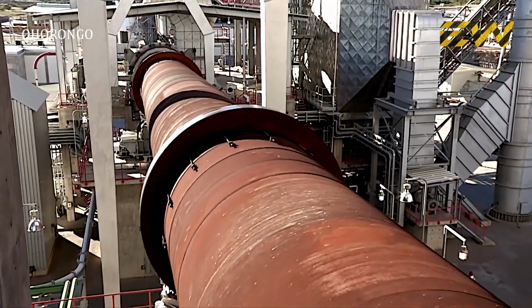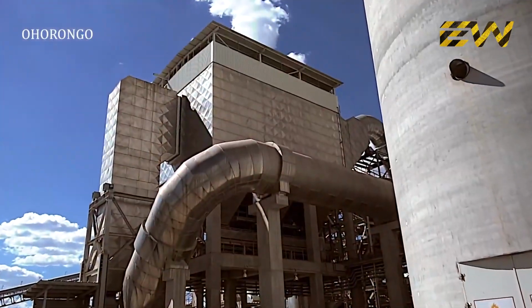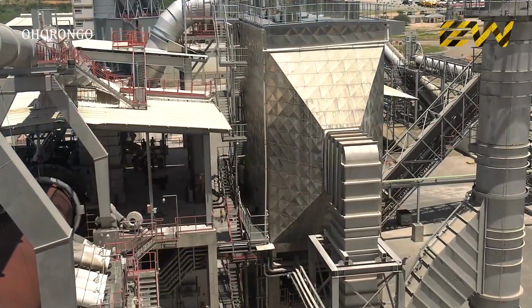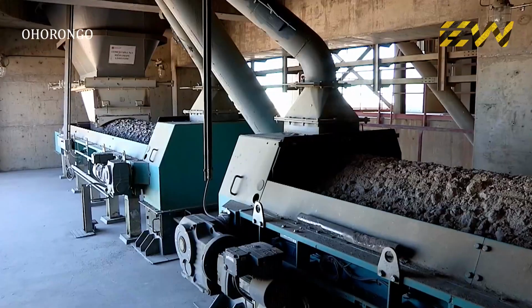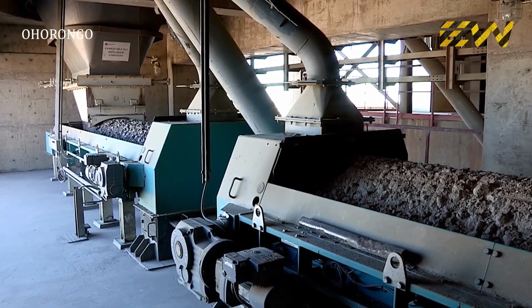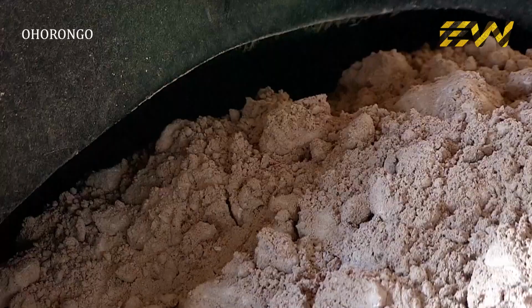The rotary kiln can produce 2,100 tons of clinker per day. The clinker is now cooled down by using a method of air quenching in a grate cooler. After the cooling process, the clinker is stored in a clinker silo with a capacity of 55,000 tons. The clinker is dosed with an appropriate quantity of gypsum and extended with high-grade limestone. Limestone extension significantly reduces the carbon footprint of the cement products.